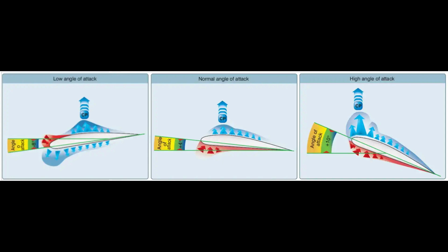In both examples, the only difference is the relationship of the airfoil with the oncoming airstream angle. A paper airplane, which is simply a flat plate, has a bottom and top exactly the same shape and length. Yet, these airfoils do produce lift, and flow turning is partly, or fully, responsible for creating lift. As an airfoil moves through air, the airfoil is inclined against the airflow, producing a different flow caused by the airfoil's relationship to the oncoming air.